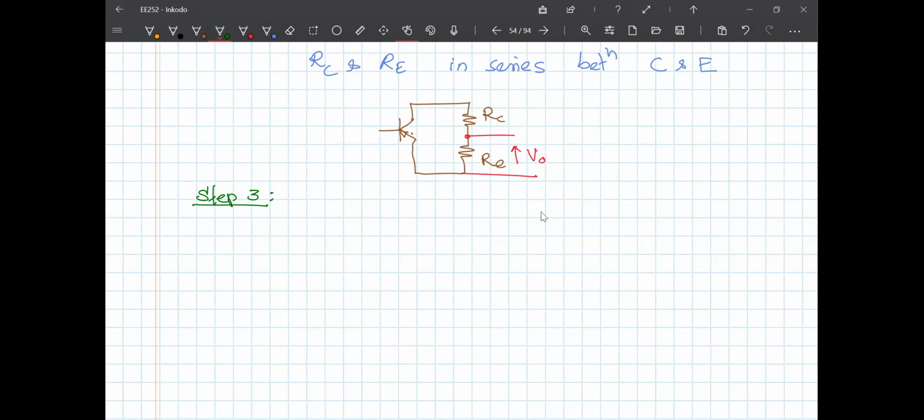Now in this case, it is very obvious. The source is itself a voltage, so it's already in the Thevenin's equivalent circuit form. But as I mentioned earlier, if you had a two-stage amplifier and you are looking at the second stage, you have to represent the output of the first stage either as a Norton's circuit or a Thevenin circuit. Now there you have to identify what the feedback signal is.